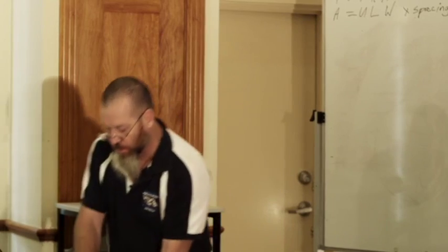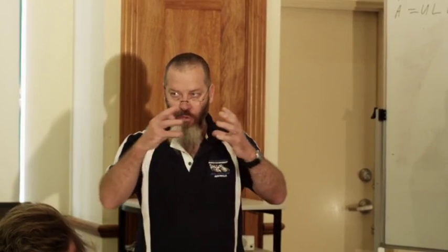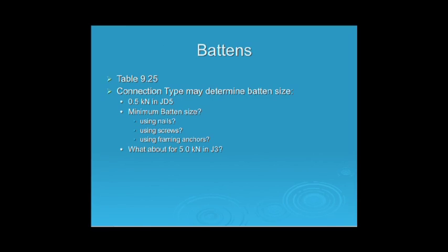So that's what these connections are all about, and that's basically how they work. The outcome in the tables on the right-hand side is the kilonewtons, but you must look at all the components of that connection. If it's a sheet roof, you can use 2 nails because you've got 75mm battens. One of the things we're really looking for in your Task 57 assignment is to make sure you've got the connection from the right table. If you go to table 9.20 for your batten connections, the red pen comes out. Have another crack at it. So that's what we're chasing.